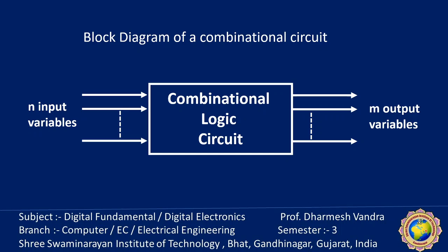Each input variable to a combinational circuit may have one or two wires. When only one wire is available, it may represent the variable either in the normal form or in the complement form. A bubble shows the complement form. Since an inverter for the literal is not available on the input wire, on the other hand, the input variable may appear on two wires, supplying both the normal and complement forms to the input of the circuit. If so, it is unnecessary to include inverters for the input.